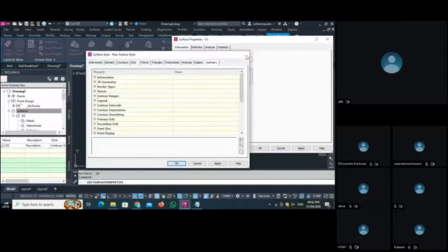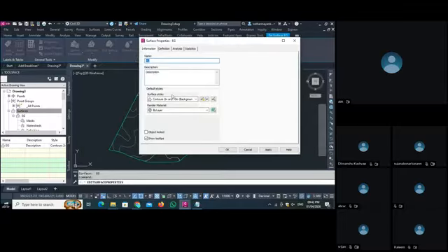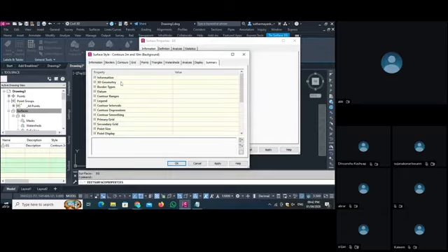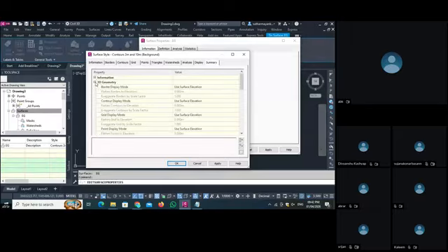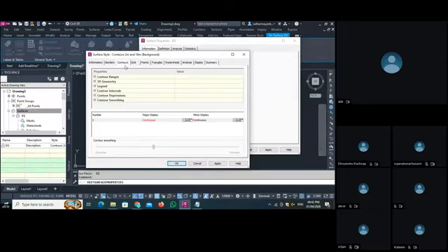But basically, these things we get as a template from the company side, so it is not a big task. But if you want to do minor editing, you can do it from here. If you want a very smooth contour, then you go here in the contour range. You can use this color scheme. In the legend, in the contour interval, you can set the interval here.